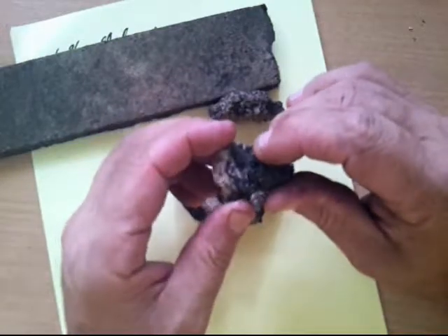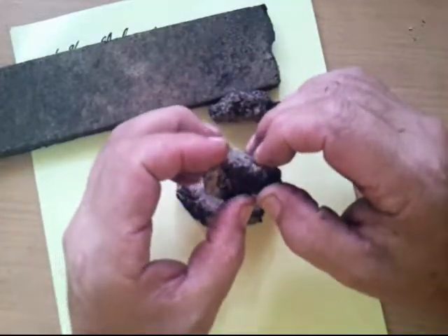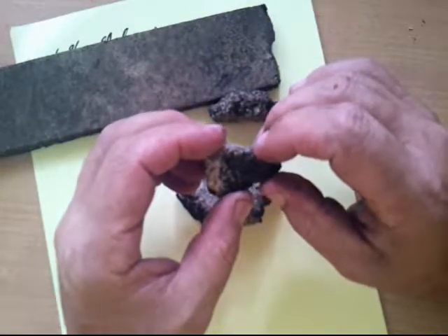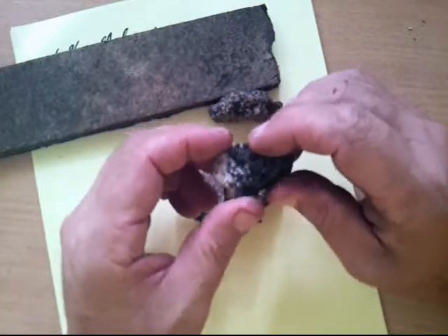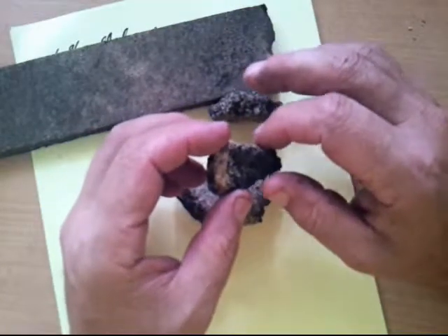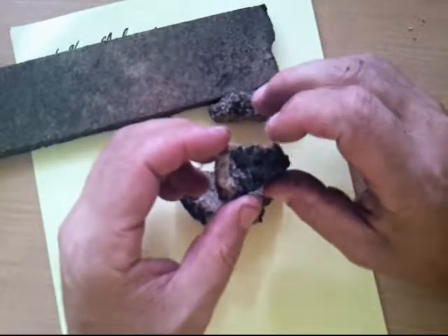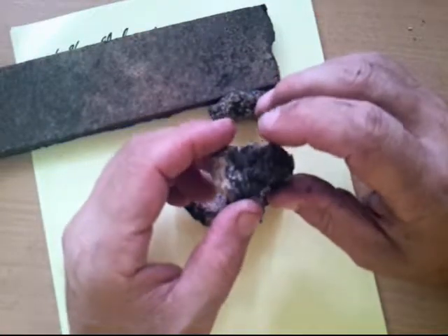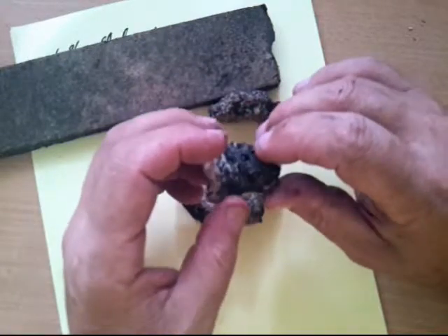Now, although it seems quite hard, almost like a rock, it is a combination of different things. It's a semi-solid item. Although it seems quite hard now, if I start to heat it up, even hot sunlight, this will start to become more plastic. The matrix, which is essentially an oil-based product, starts to flow, and you'll be able to move it and shape it. And you can see that on a very hot day. You'll be able to see deformations when there's been pressure put on roadways which are made with asphalt.